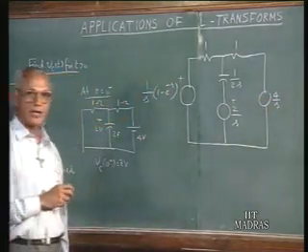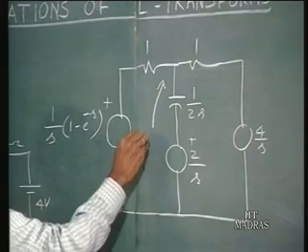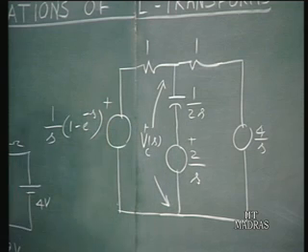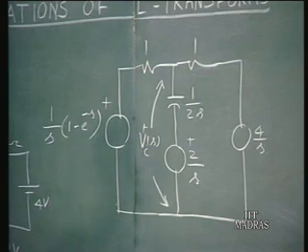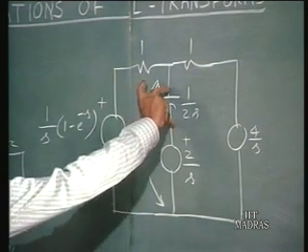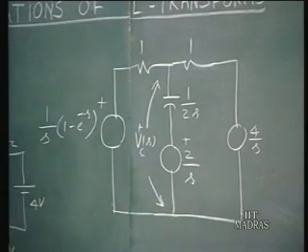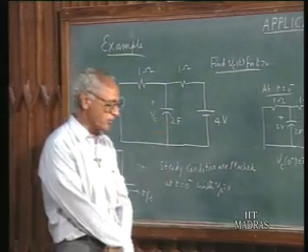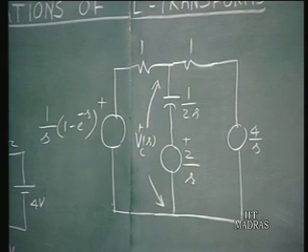Now the capacitor voltage is what is required. So it is the voltage across these two nodes. This is Vc(s). As pointed out in the last lecture, when you are interested in finding the capacitor voltage, you should not try to measure the capacitor voltage across this portion only, because it is the totality of these two together that represents this 2 farad capacitor, including the initial condition source. So when you want the capacitor voltage, it is the voltage between these 2 points which has to be calculated.